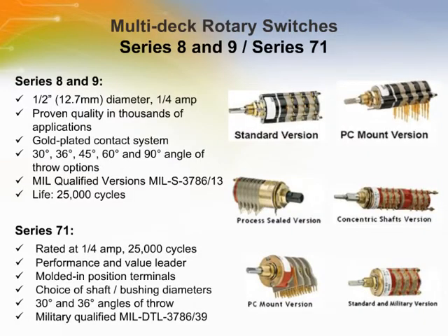Grayhill's multi-deck rotary switches provide almost unlimited circuitry options through unique combinations of decks, poles per deck, and positions per pole, as well as concentric shafts. They can be specified as fixed stop, adjustable stop, or continuous rotation. Electrical specs can be chosen from low current wiping contacts to high current UL type to fit your application. Custom shafts, configurations, sealed assemblies, and mil-spec versions are also available.